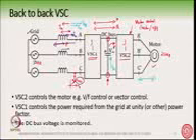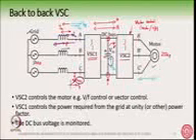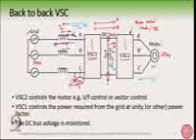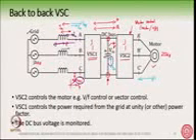So this DC bus which was increasing will now stabilize. This VSC1 is a very important phasor in this whole system, apart from the DC bus voltage. If the DC bus voltage is fluctuating, VSC1 can be controlled or changed so that you can feed power into the grid, or you can absorb power from the grid.